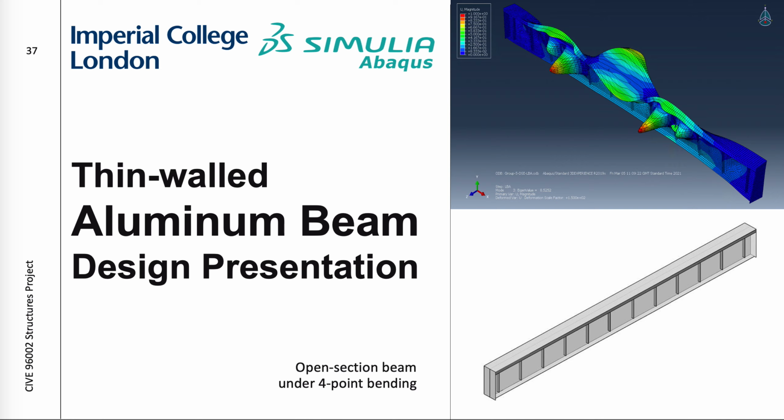In conclusion, the design can be summarized by a set of seemingly contradictory statements. Initial hand calculations resulted in a beam design that was expected to fail due to web buckling at 13.5 kN. However, lateral torsional buckling, a mode that was under-designed for due to incorrect assumptions about lateral restraints, in fact turned out to be the most critical during LBA. Yet despite this unexpected failure mode, the beam turned out to be too safe, with a failure load above the brief's limit. Fortunately, when imperfections were added to the beam, the critical combinations of imperfections gave a critical failure just above the minimum required.